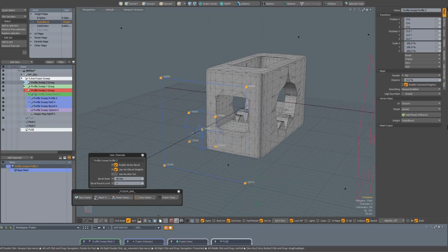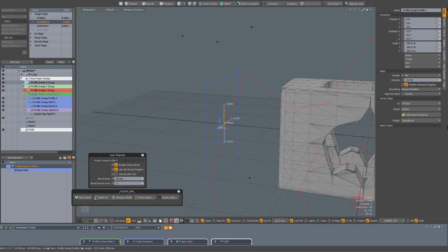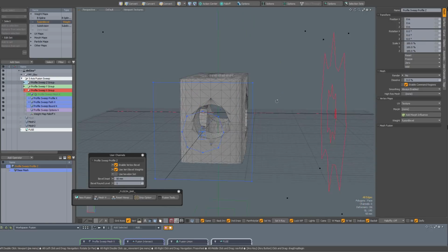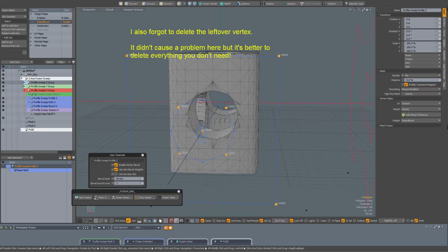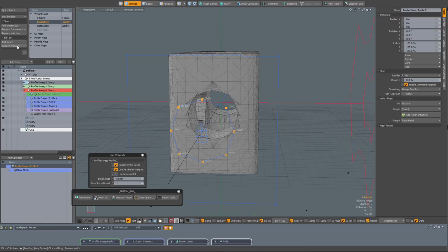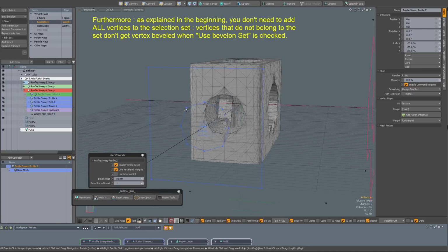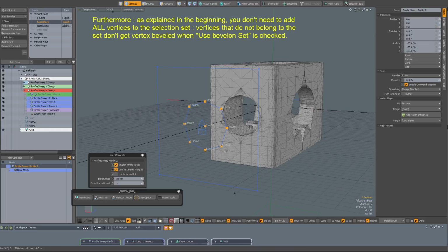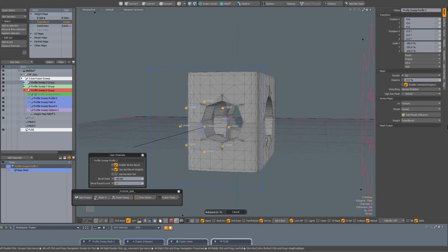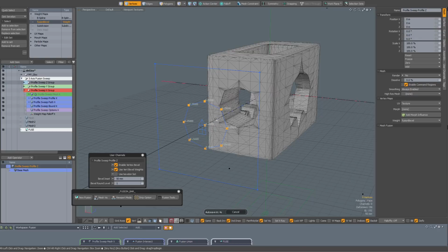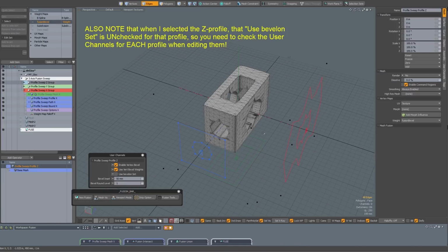do not belong to the set, and furthermore I should get rid of those edges, so select those edges, Shift Backspace, that's better, go to vert mode, quick select, bevel on, those middle edges do. So middle vertices do not belong, so select them, add to set, W for the weight, maybe 25%, click, and now they are sharper, just like that. And of course I can do something similar for my Y axis.